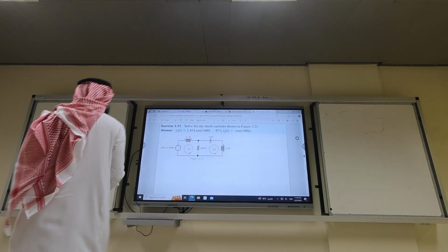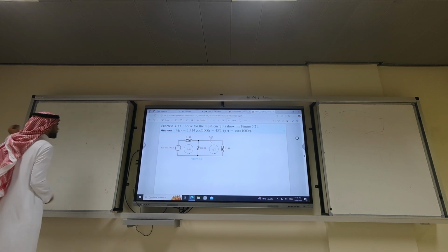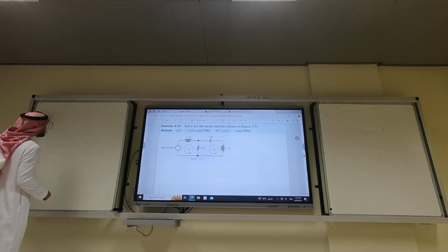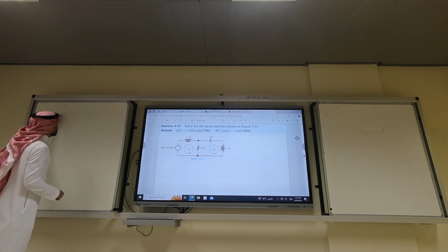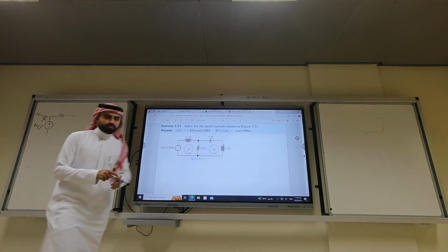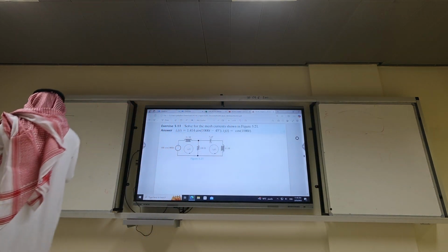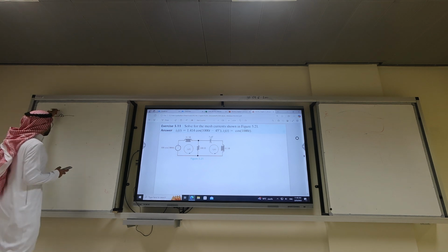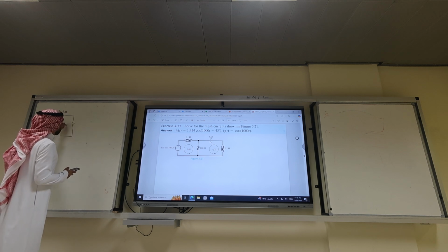We're professionals. Start with the voltage source. What's the phasor? 100 angle 0. What's the omega? 1000. Then we have an inductor. Convert it quickly. 0.1 times 1000 is 100. 100j ohms. A resistor of 100. Keep it, right?